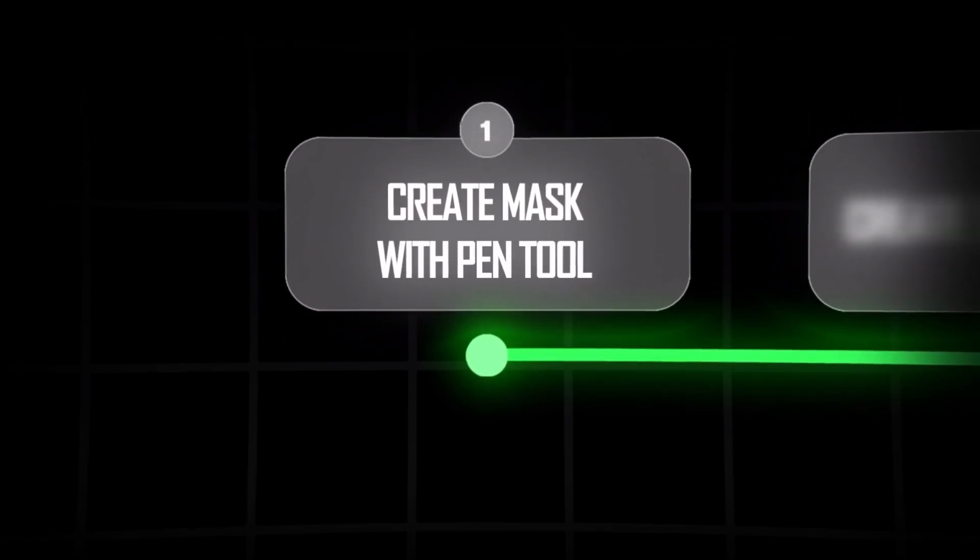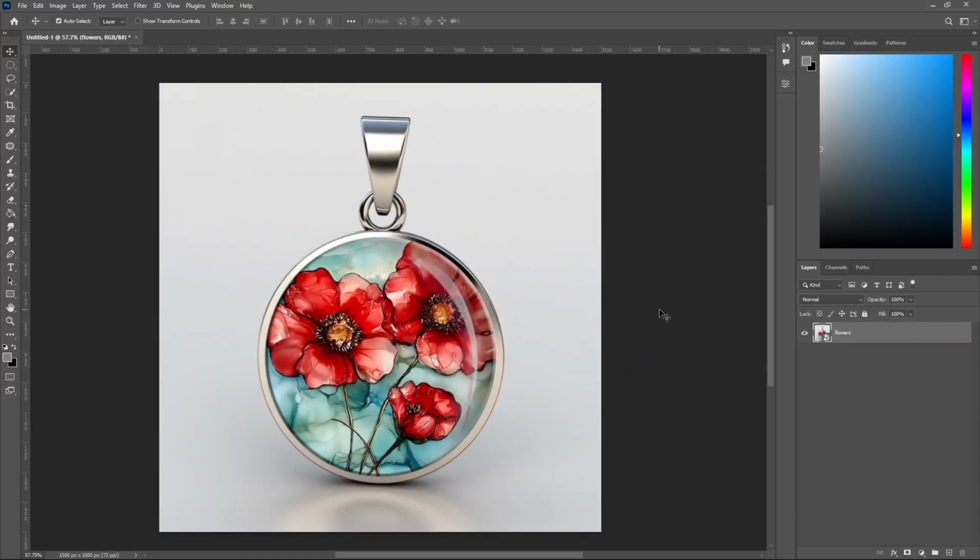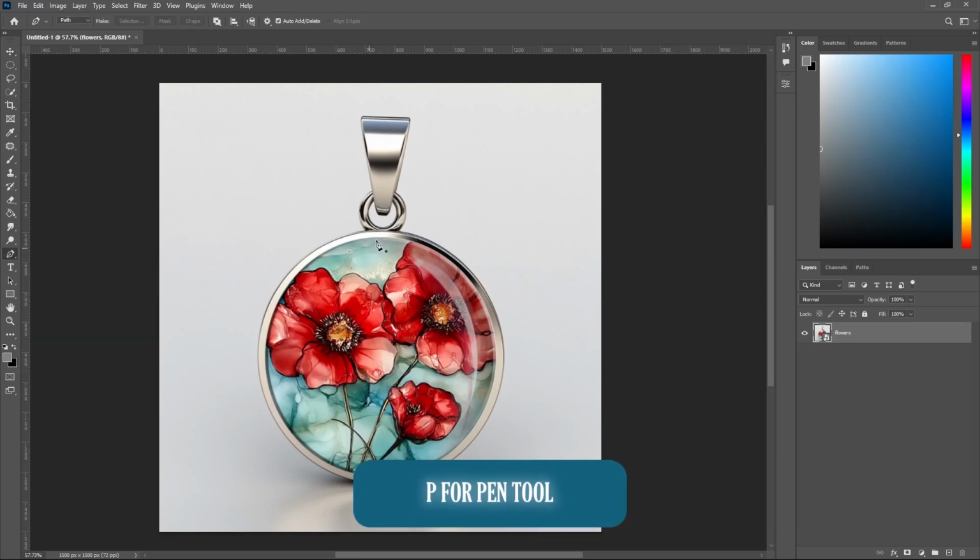Step 1. Create mask with pen tool. Alright, let's start by creating a precise mask for our circular object using the pen tool. If you're new to the pen tool, don't worry. I'll walk you through it step by step. First, select the pen tool from the toolbar or press P on your keyboard.